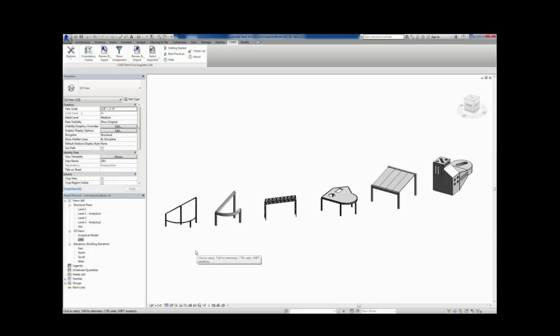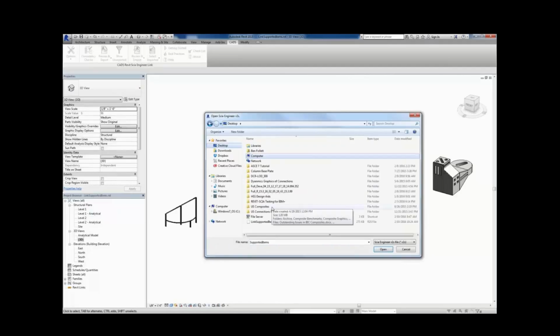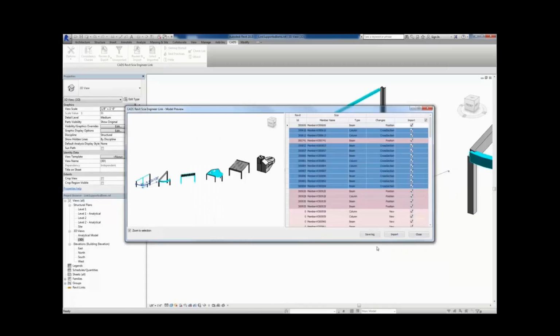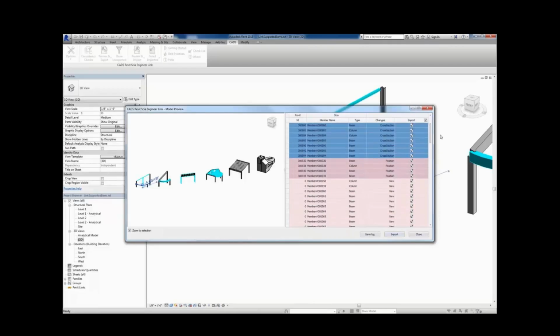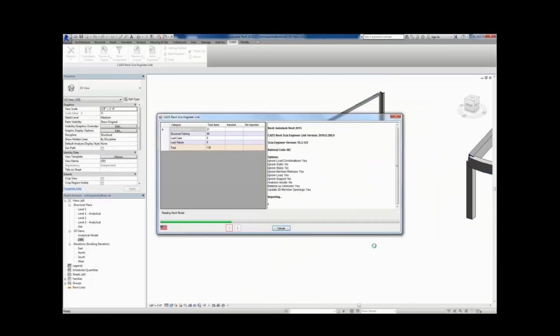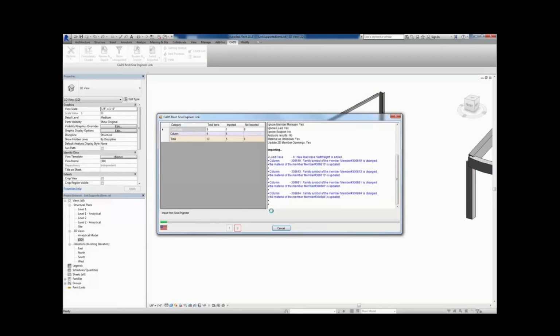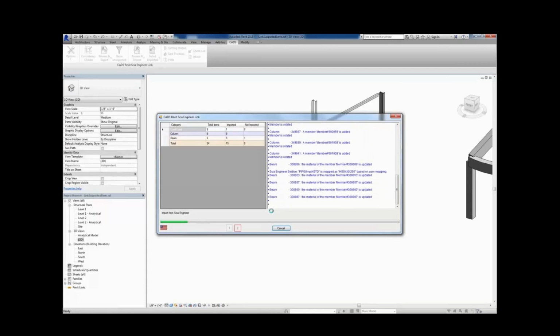So we can then jump back into Revit. We can review and import, and we choose our R2S file. Then the bidirectional link will show us highlighted the members that were originally there, and also any changes, highlighting those changes. We have some flexibility in whether we want to accept the changes and which ones, and then we can perform the import.